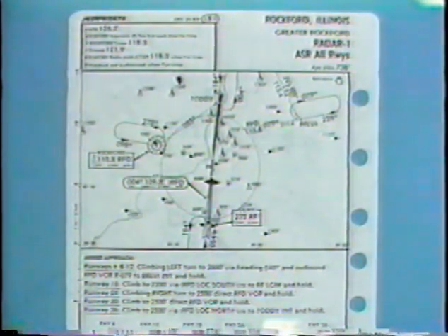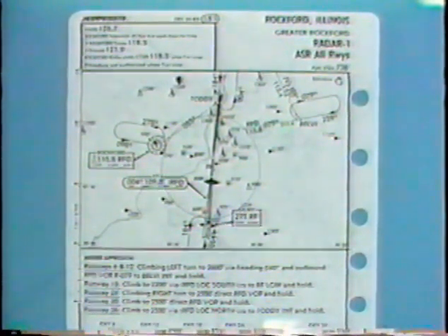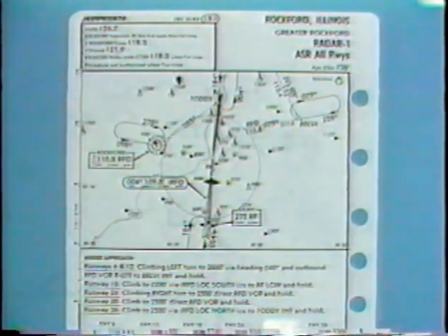If on the final of an ASR approach the pilot receives no communications for 15 seconds, the rules require a missed approach. At fields where there are published ASR approaches, Jeppesen publishes separate plates for ASR approaches. Controllers are required to maintain ASR accuracy, so they are often willing to provide practice for you, the pilot, when their workload is not too heavy.